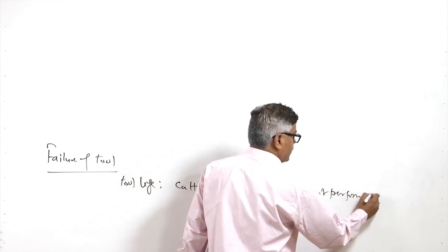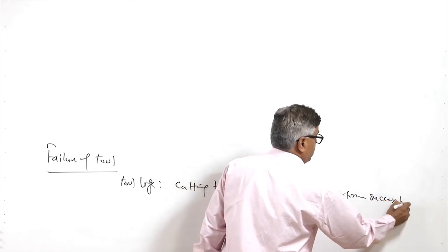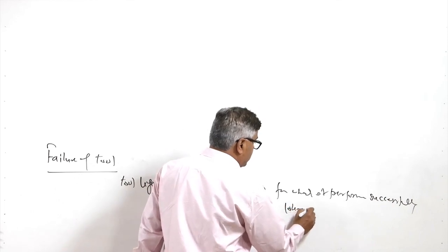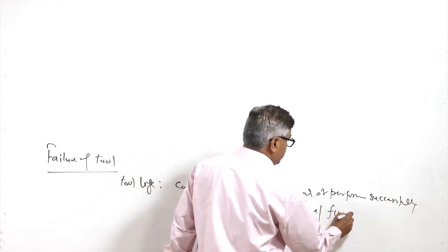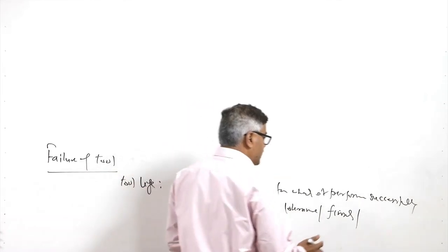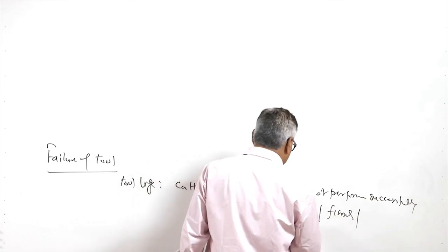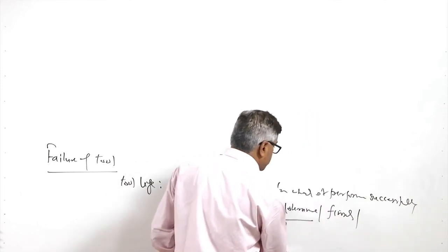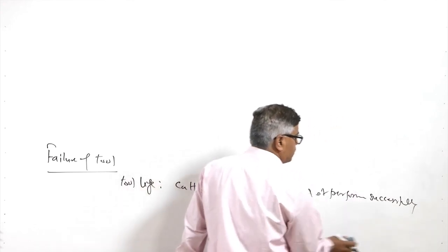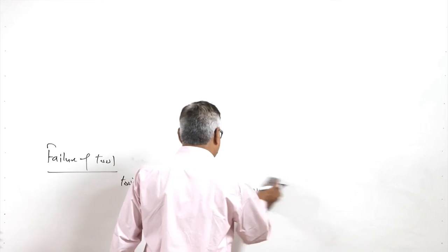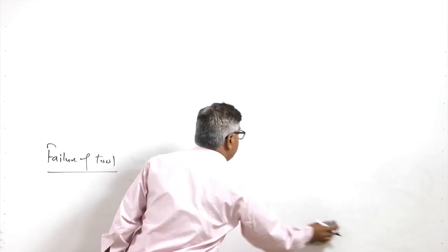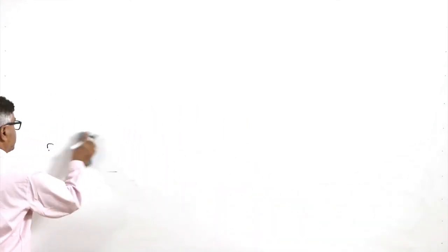So, what is that? It should keep on giving us the required tolerance during the machining, the desired surface finish, and no unnecessary rise in specific power consumption. So, the tool should perform satisfactorily so that it gives us the desired tolerance and surface finish. So, the time for which it can be used during the machining decides the tool life. It is normally expressed in terms of minutes.